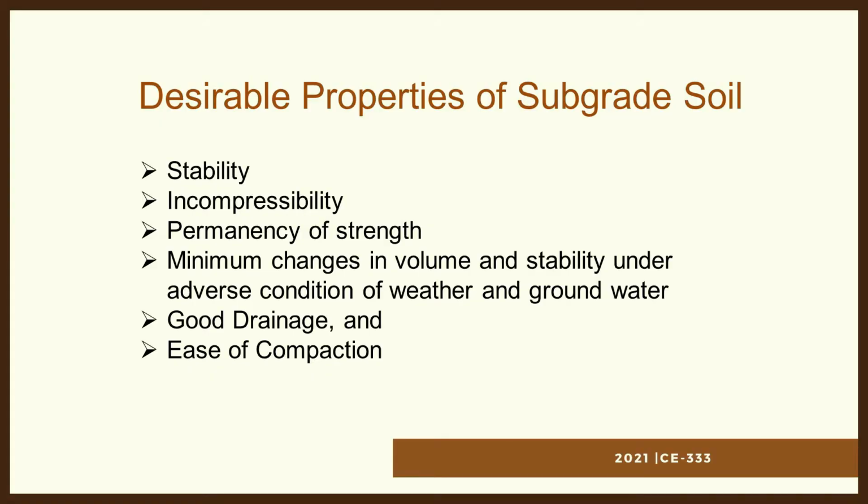Here are the desirable properties of a subgrade soil. The first one is stability, wherein yung subgrade soil must have the capacity to resist the permanent deformation under the traffic loads. So, the next one is incompressibility, wherein yung subgrade soil should be well compacted o siksik talaga siya in order to prevent the compressive under the heavy traffic loads. And pag kasi yung subgrade soil is well compacted or siksik na mabuti, it will provide a good support to